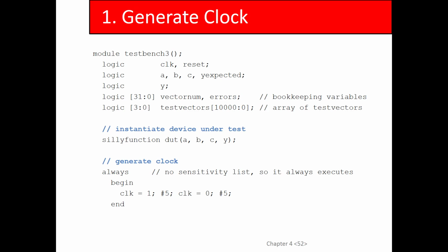A pitfall here is you have to keep in mind that in Verilog, when you have a multi-dimensional array, a two-dimensional array, the width comes first and the depth comes second, which is the opposite of how Java and C declare two-dimensional arrays. The way I remember that is because if you normally declare a multi-bit signal, you would put the width first, right?